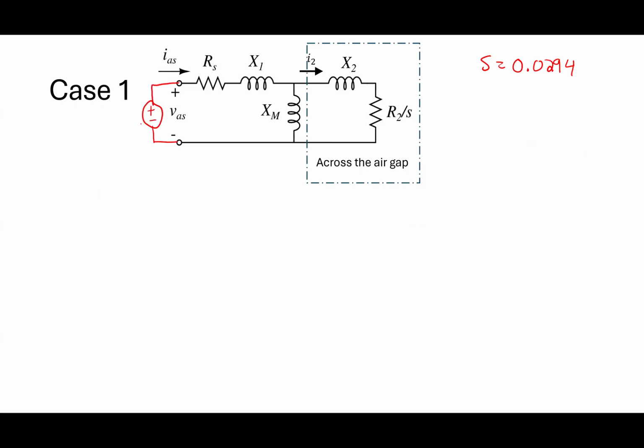The important thing is this is a single phase circuit model. There are 3 phases on this machine. Each phase is operating the same way. The only difference is a phase shift on the voltage sources connected to it. If I want to figure out I1, that's basically the current flowing in here. So let's call it I1 like that.